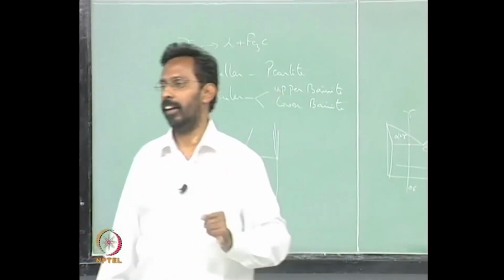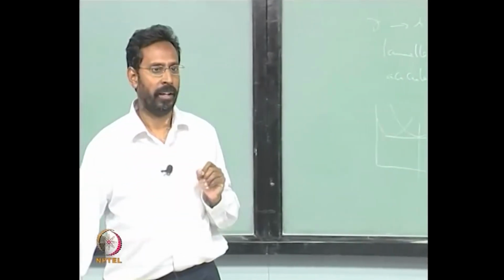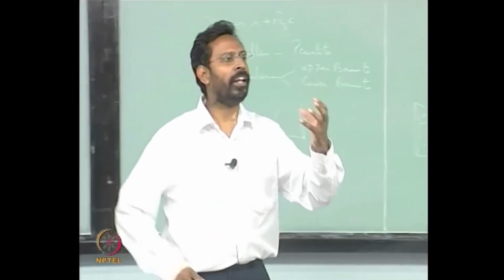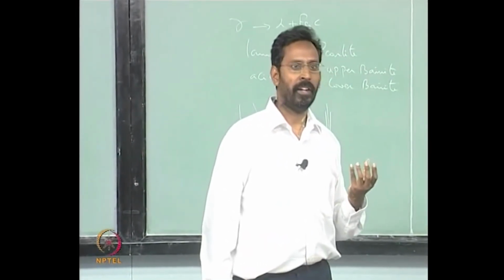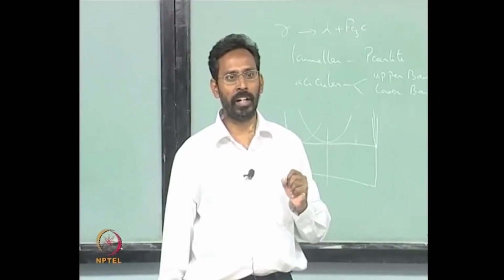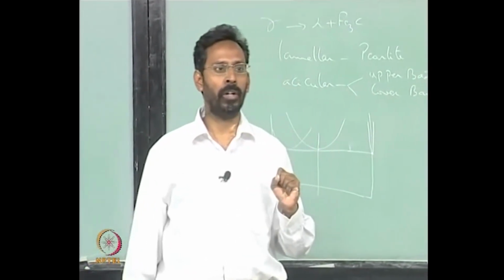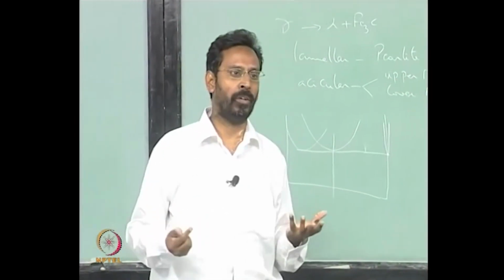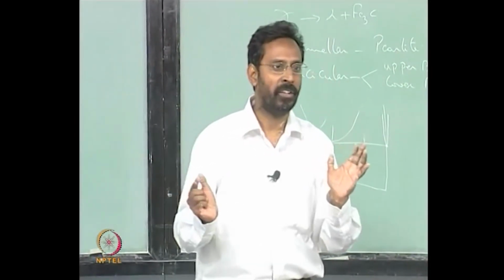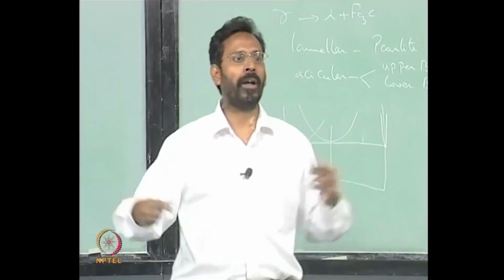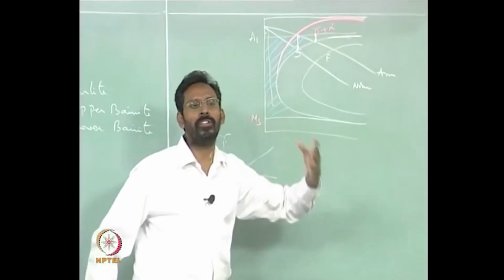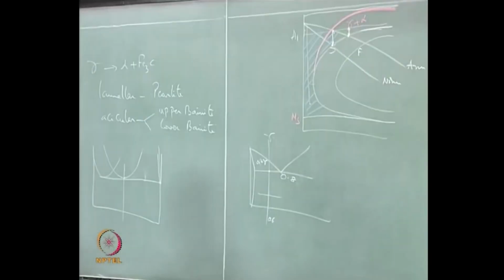Pearlite colony size again is going to be smaller. When I say nucleus here, a pearlite colony gets nucleated; it is not a simple single phase getting nucleated. So when I say the nucleation rate is higher, a number of pearlite colonies are getting nucleated within a particular grain. One grain is broken into a number of colonies if the undercooling is higher. If the undercooling is smaller, you will see fewer nuclei, that means bigger colony size.